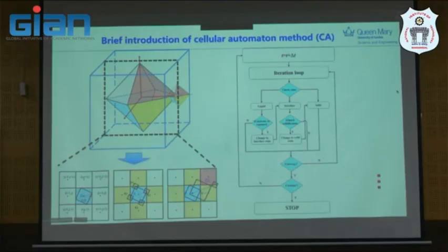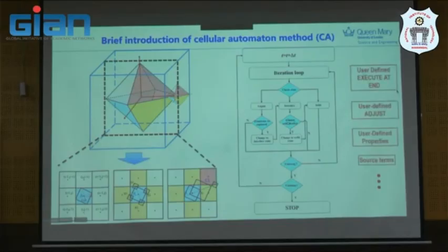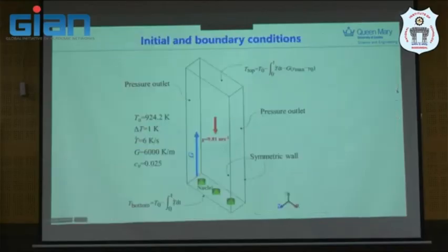As the state and the solid volume fraction are updated, the progress of the melting solidification is predicted, which means we use this progress to simulate the dendritic grains growing. And in this simulation, we will use these macros. And here are the initial and the boundary conditions for our simulation.